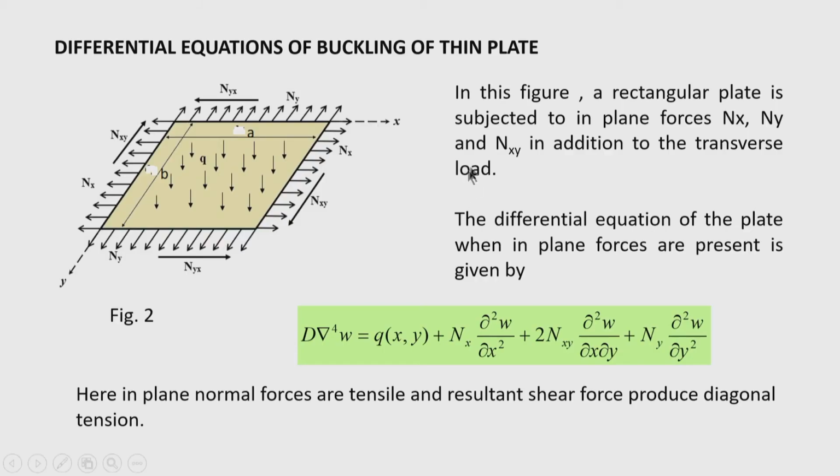So, here you are seeing in this figure a rectangular plate subjected to in-plane forces N_x in the x direction, N_y in the y direction, and N_xy is the membrane shear force acting along the edges. So, these are the membrane forces N_x, N_y, N_xy, and the equilibrium equation connecting the membrane forces is known to you, and it is similar to the plane stress equilibrium equation.